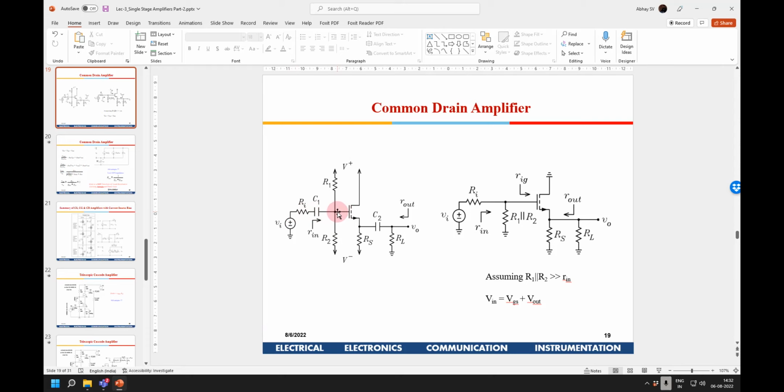My question is, we don't even need R1, R2 when you club these two, common source and common drain. No, there could be a problem. Say for some reason, for my design requirement, the DC operating point of the first stage is only 0.5 volt, whereas the DC operating requirement here is 1 volt, suppose. So universally, I cannot do that. For specific requirements, I can connect it.